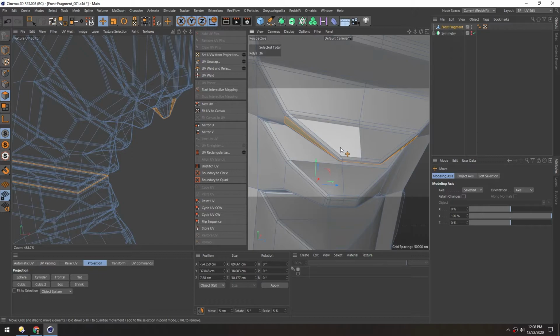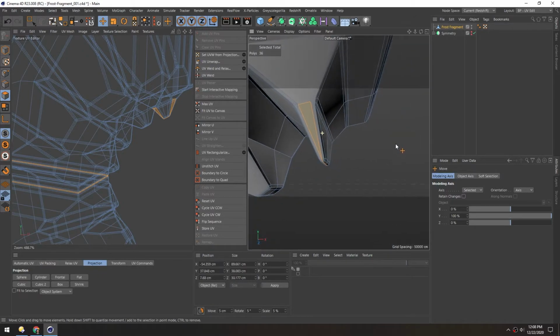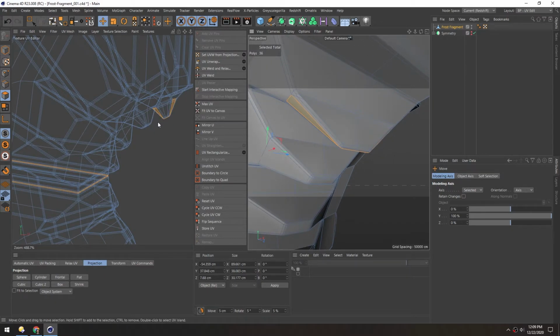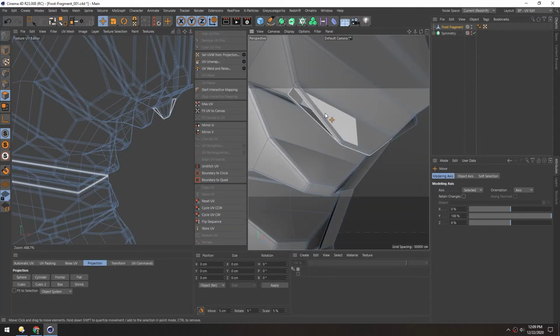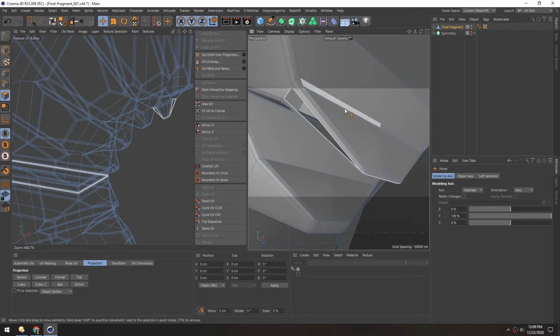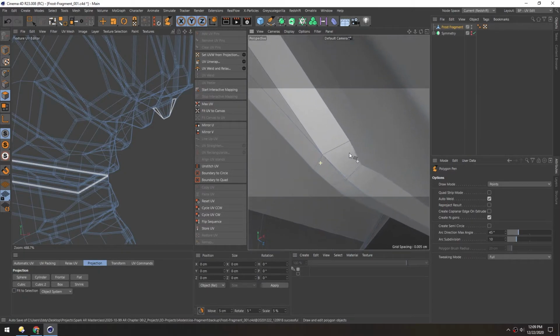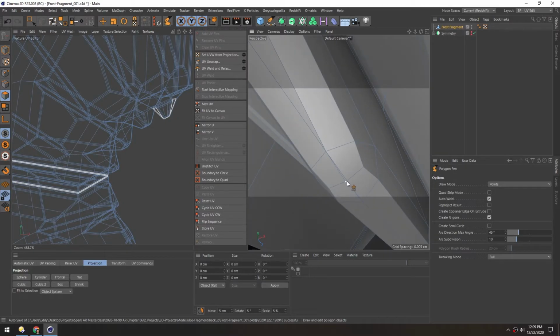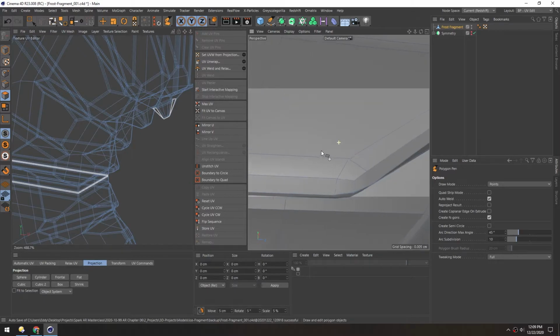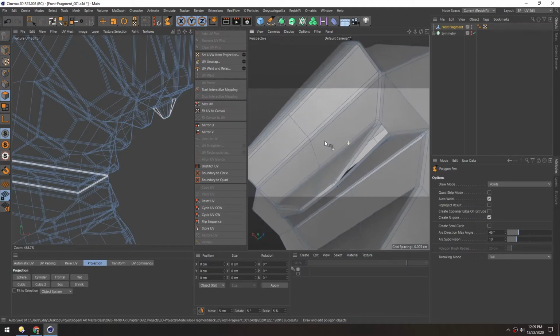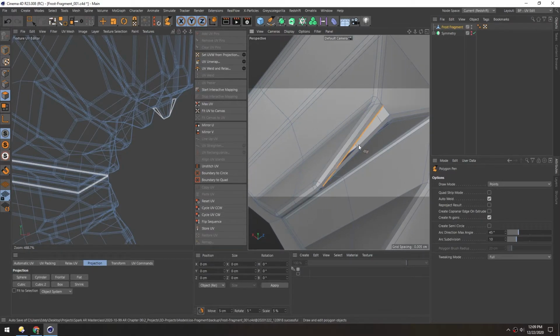Now it looks like there's a couple polygons that got created that are basically infinitely small, or they're inside out. So it automatically selected those. I'll hit delete, and that'll clear those out. And then it looks like we just have to fill in a couple of polygons. So I'll hit ME to go to the polygon pen tool, and then control drag this edge to duplicate it. And that closes that hole. And this, I'm just going to manually close that. Same with this one. And this probably happened when we were doing the beveling, because the bevel sometimes adds some bad geometry.